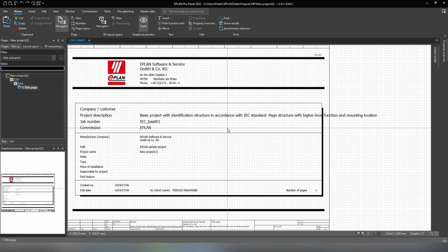The reason is that sometimes the project was created in a different version. Maybe, for example, it was created in the 2023 version, or in a 2.9 or 2.5 EPLAN version. So it sometimes pops up an error asking, are you aware that the project was created in a different EPLAN version? Do you want to open it in this version? So I would suggest you just go to File Open, and once you do, you can actually see before trying to open the project that it was created in 2.9, or 2022, or 2023.